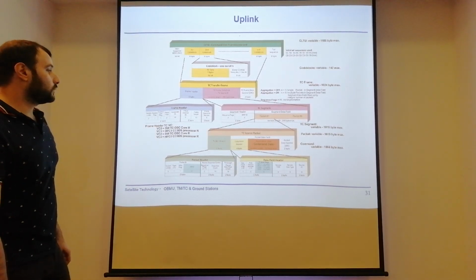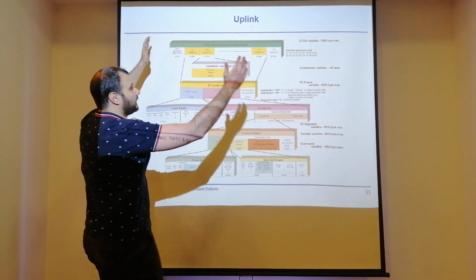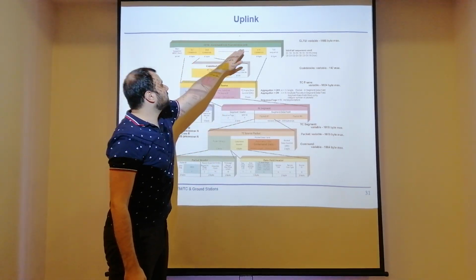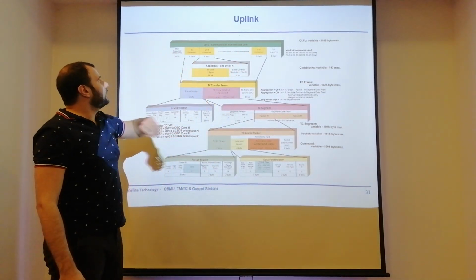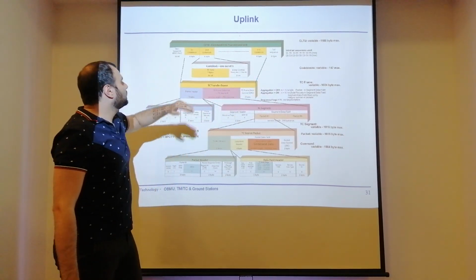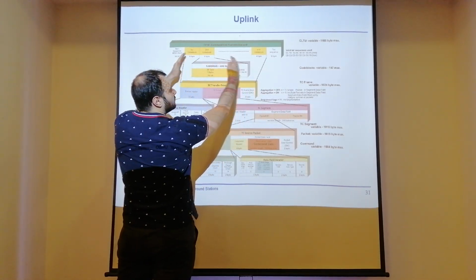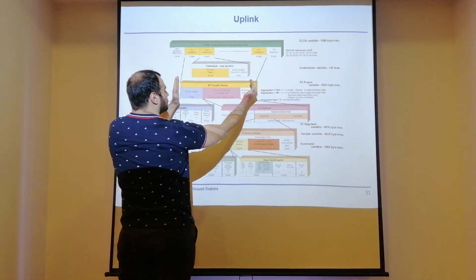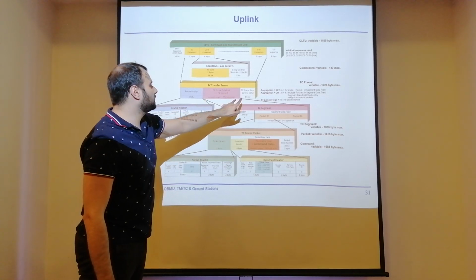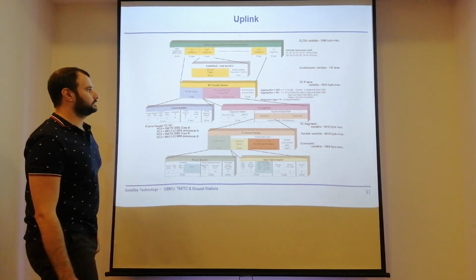And this is one example for the uplink, how it's organized. We have our data in so-called CLTUs, the Command Link Transmission Units, with different headers and footers. We have some code block introduction, and between the CLTU we have the transfer frame, with a frame header, our TC frame data, and our TC error control.